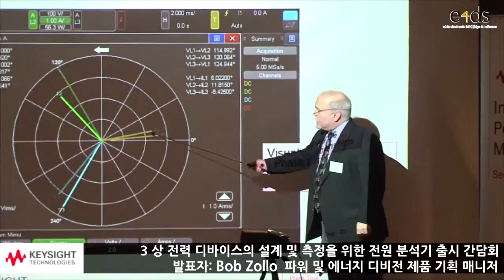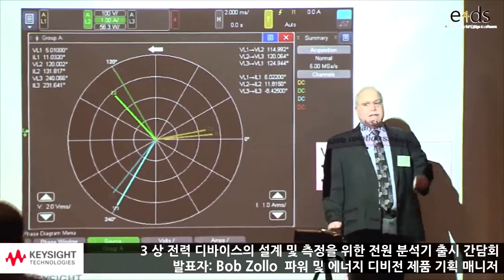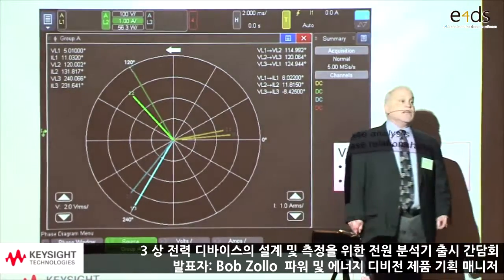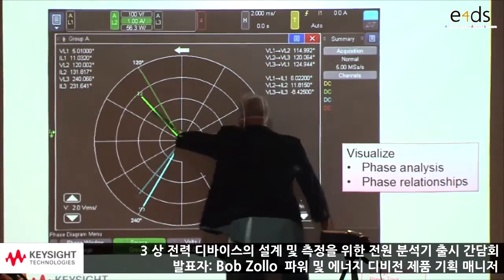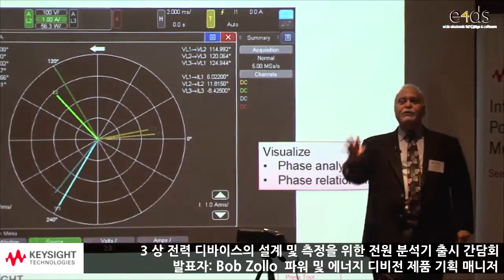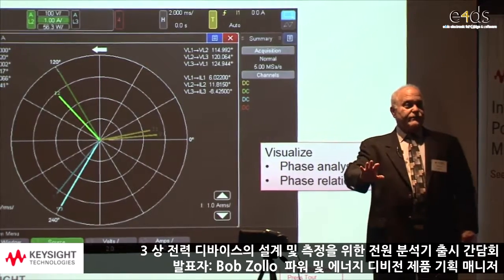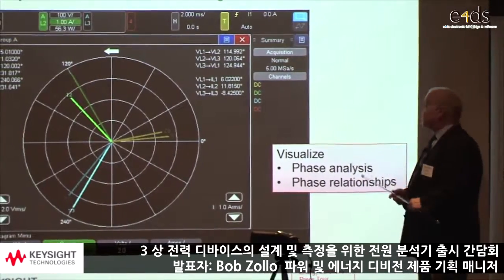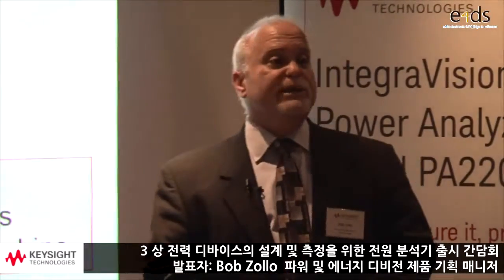The lines represent the voltage and current on each phase. If you are connected correctly, these lines will line up with the 3 phases. If you're not connected correctly, one of these lines will be somewhere else on the chart. So it very quickly verifies that you followed the instructions from the previous graphic to this one before you begin making measurements. Once you've configured it properly, once you're certain that it's correct, now you can go ahead and make measurements and be confident that you're making the correct measurements in a safe way.